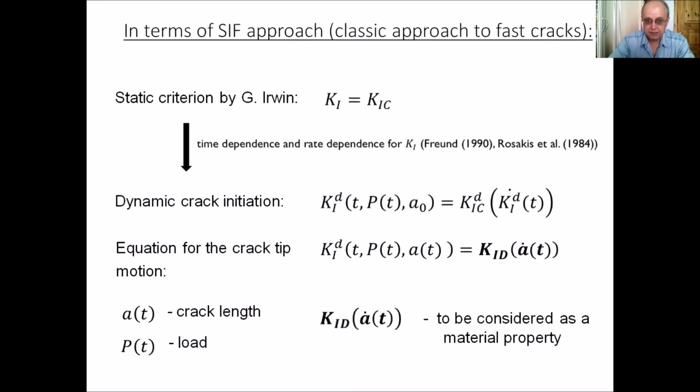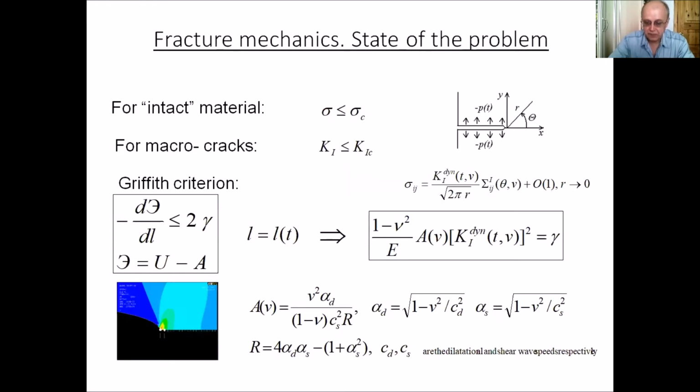My starting point is classic fracture mechanics. The statement of the problem arises from the classic principle associated with strength and fracture toughness. It corresponds to the basic idea of energy balance, so that we must have the required amount of energy released per unit of new surface to produce fracture at the crack tip. And the specific energy ought to be a material property.